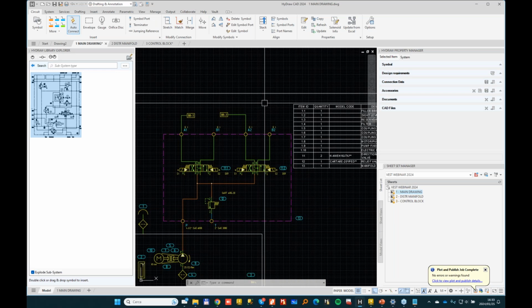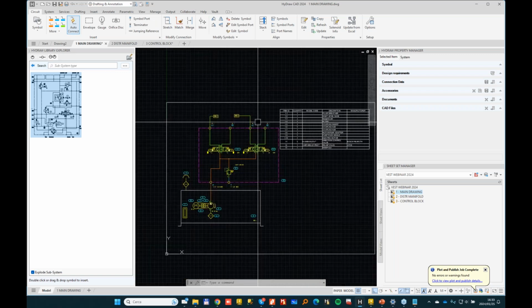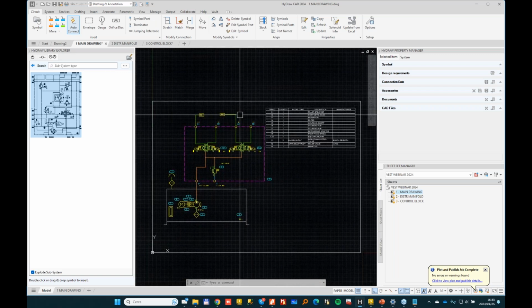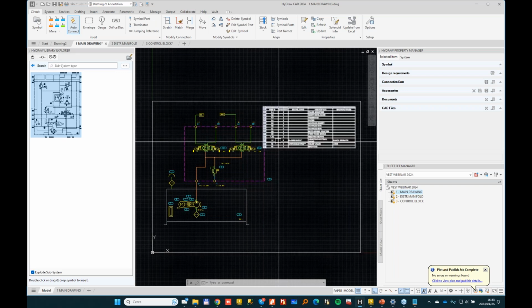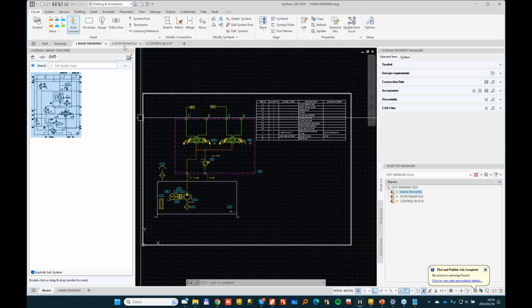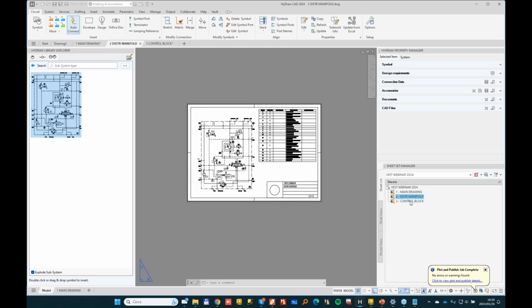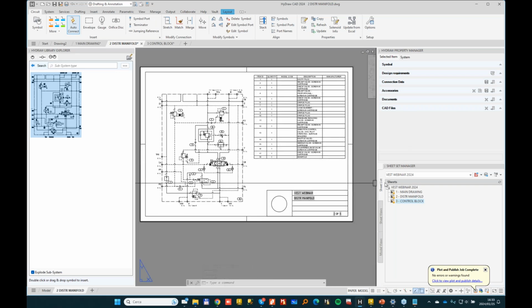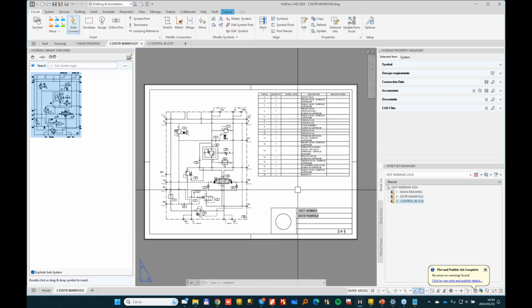The biggest benefit I can see in using sheetset is that all the operations are faster, lighter, because the files normally are smaller. There are not too many components in the same drawing, and you can switch between documents really quickly. You don't waste too much time with plotting, because basically if you do good template, then all the pages are preset for plotting, very well configured.